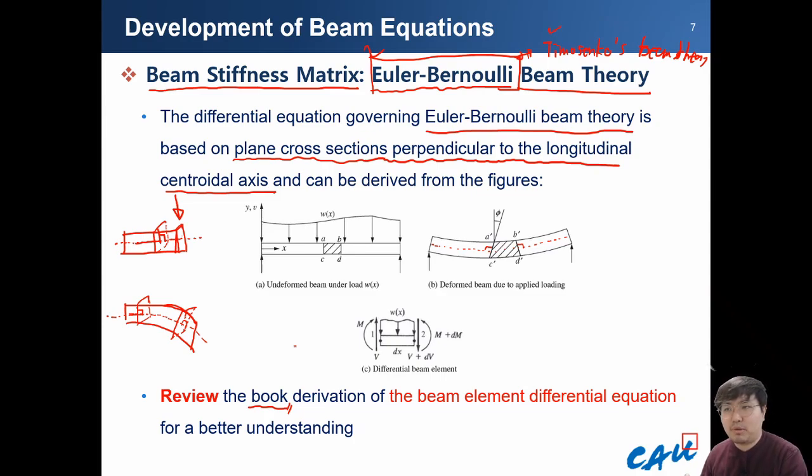For example, in beam theory, Timoshenko assumed that the cross section does not stay perpendicular to the centroid axis anymore. This is the starting point. It is because a solid structure shows a slightly different behavior in the transverse displacement. So Timoshenko wanted to explain it more accurately than Euler beam theory. Many researchers developed their own theories by adding to the basic assumptions.